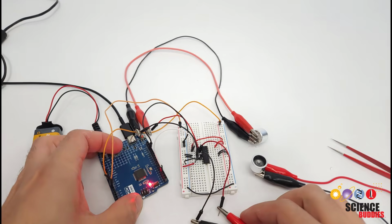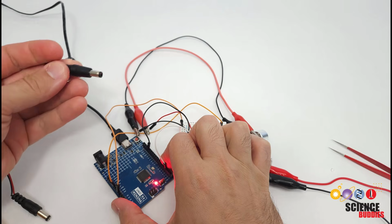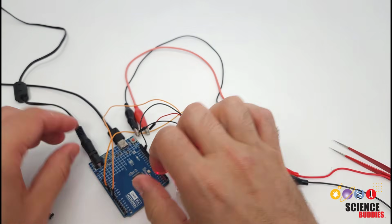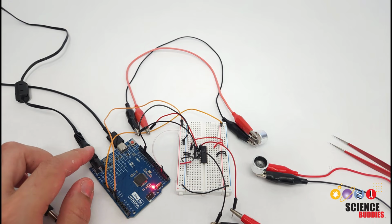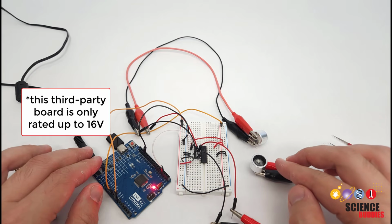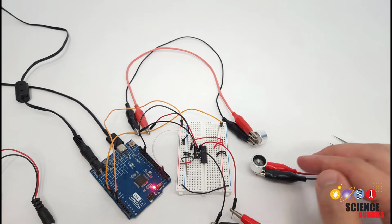So, changing my camera angle again so we can see the circuit better, I'm going to unplug my 9-volt battery, and I have a 12-volt 3-amp wall adapter, so that can provide a lot more power, and I'm going to plug that into the Arduino instead. Now, you need to be careful here because the Arduino can only handle a certain voltage range on this barrel jack. So on the Arduino Uno R3, that's going to be up to 12 volts. On the Arduino Uno R4, it's up to 20 volts. So if you want to power your transmitters with more than 20 volts, then you don't want to plug directly into the Arduino because you can damage the Arduino board.